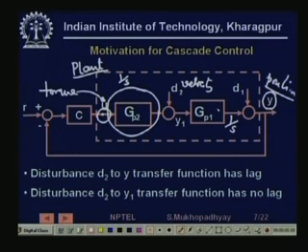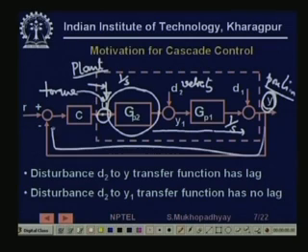Now in this situation there can be disturbances everywhere. For example, there can be load disturbances. So where does the load disturbance come? The load disturbance can come in various places. In the case of the motor, it can come at the input itself, because total electromagnetic torque minus load torque will give you the net torque. So if a load disturbance comes here, this must traverse through this whole process and then it will affect the output, and then it will be fed back and then there will be error. So it takes a lot of delay.